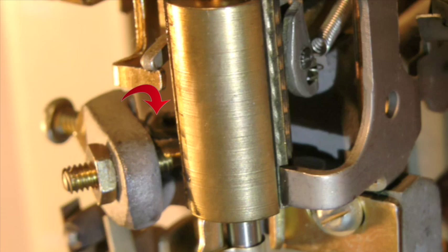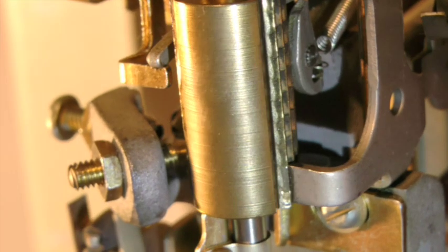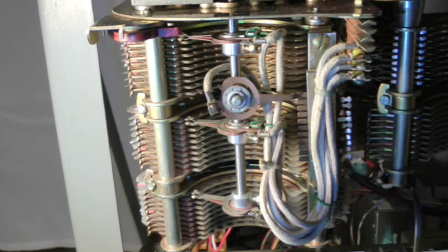Attached to the rotary armature is the rotary pawl, which now engages the rotary ratchet and steps the shaft and all of its attached apparatus horizontally clockwise by one step. This steps all 3 sets of horizontal wipers into contact with the first rotary position terminals on the 10th level.